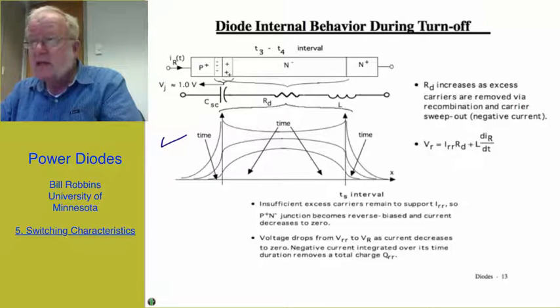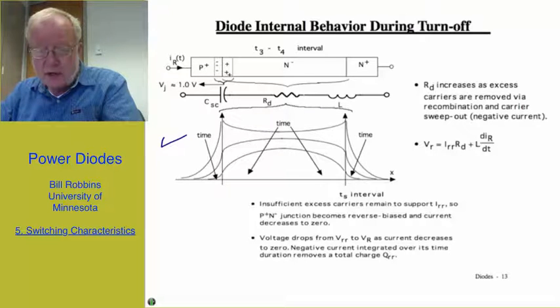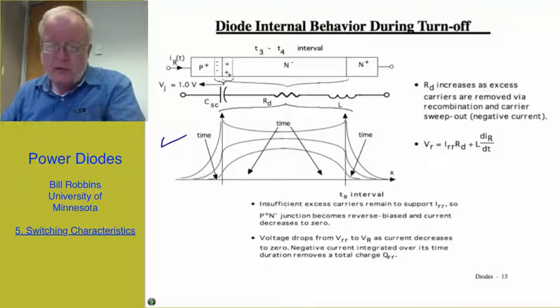And so in that case, where we may exceed the breakdown rating of the diode, we're going to have to do something. That could be either in the form of using diodes that have higher ratings, and secondly have a softer switching characteristic, not so abrupt. In other words, the time T5 is larger. Or we may have to put in special circuit components to implement what we call a snubber to prevent the voltage from being so large.